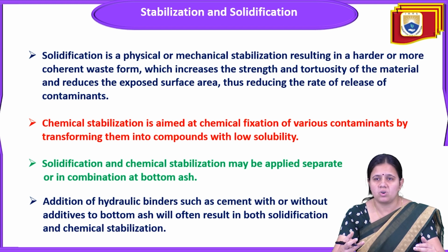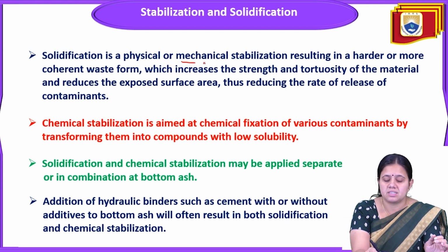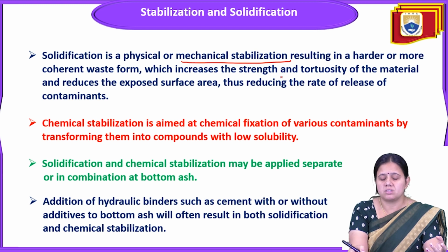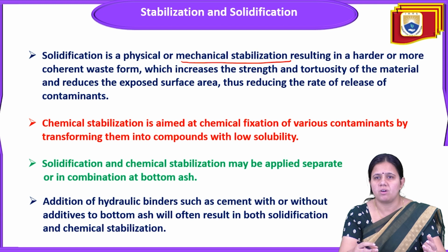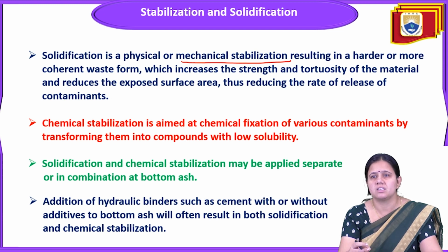The physical process involves mechanical stabilization. It will result in a harder, more coherent waste form, which increases the strength and tortuosity of the material and reduces the exposed surface area, thus reducing the rate of release of contaminants.